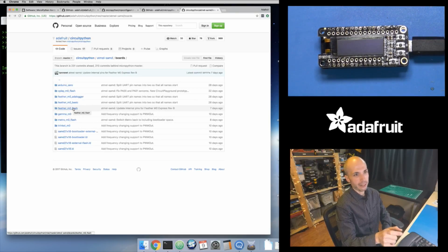There's a SPI flash chip where we can store the user file system with all of your Python code and all of your assets and other files. We put that into an external flash memory chip, and then all of the flash memory built into the microprocessor can be just for the MicroPython firmware. So all of that 64K or 128K or however much memory the SAMD21 has, all of that can be for MicroPython, and so that gives you a little more extra room to add back in these modules like framebuffer.